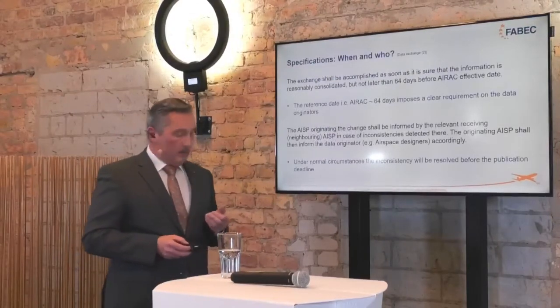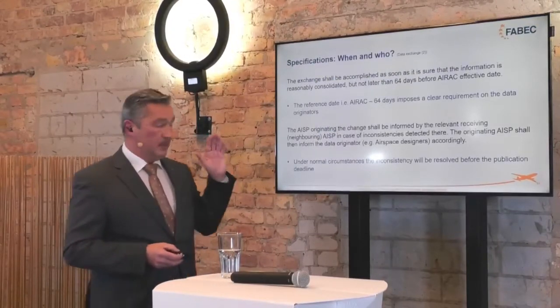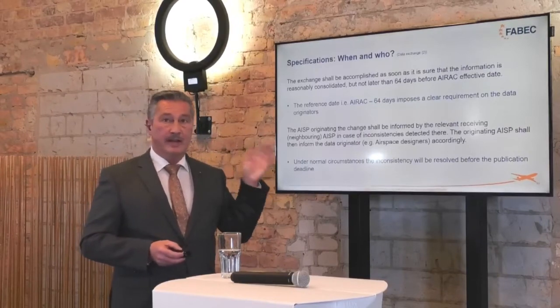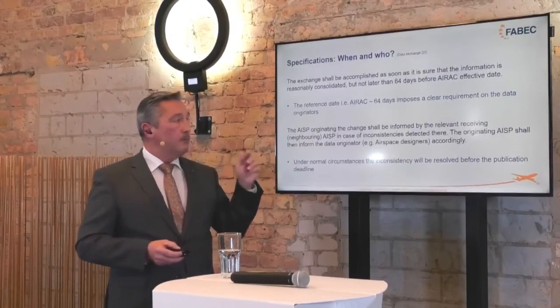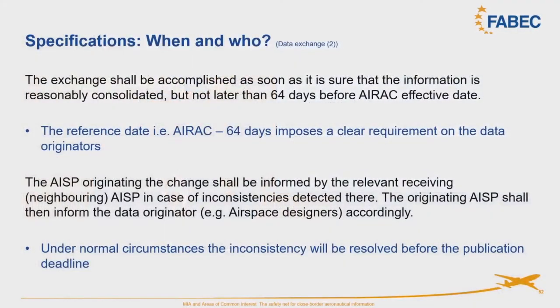Okay? The when and the who. This was an important bit, and we discussed this at length. The outcome was that in principle, later on, we agreed on 64 days prior to the AIRAC date that this information must be there, which of course imposes an obligation on the airspace designers. They must not come with requirements for publication later than that. That is very important. We didn't have this before.